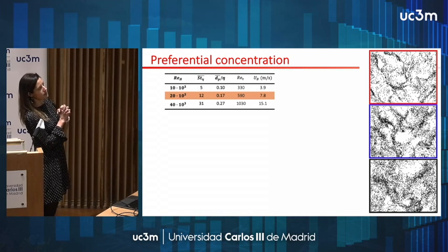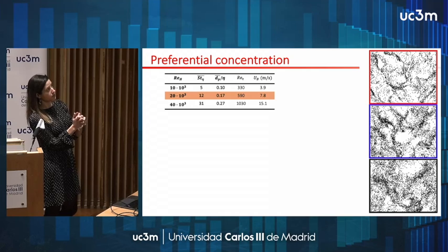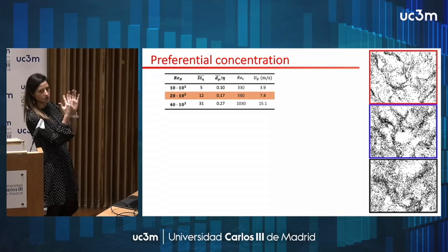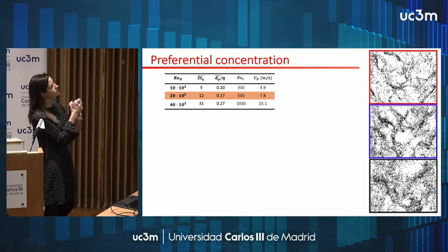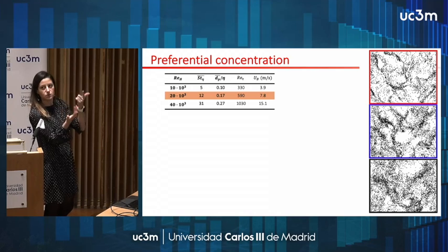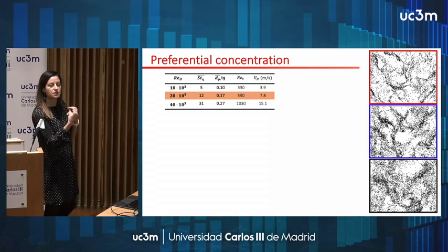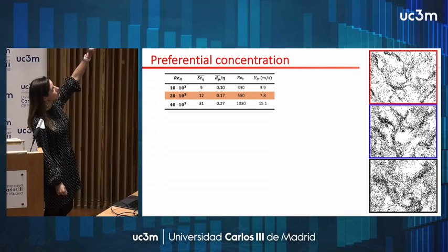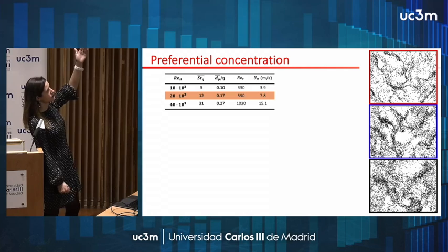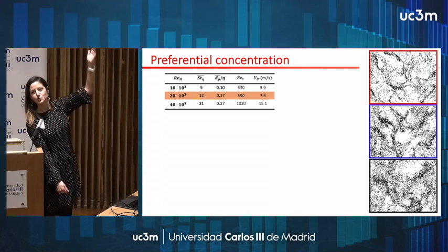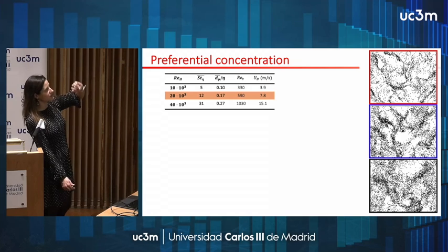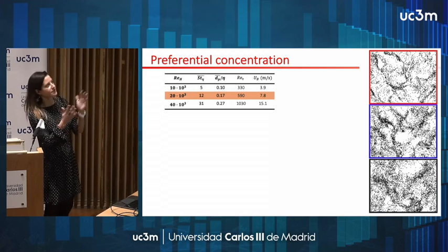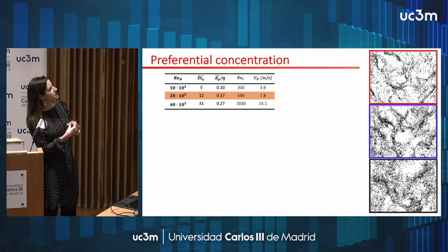What is different in here? Those are experimental images. We have the same particles, solid nickel particles, 12 microns small. They are inertial, in the Stokes regime where they do preferentially concentrate, and we vary the flow. Remember that the Stokes number depends on the flow and on the particles, right? So you can change the number in one way or the other. So 3 different velocities, 3 different Reynolds numbers, and 3 different Stokes numbers: 5, 12, and 31. So which one is which, right? They have more or less the same loading. The picture that I took from the top one looks like it has fewer particles. Well, bad luck on the one I chose, but the loading is the same in all of them.